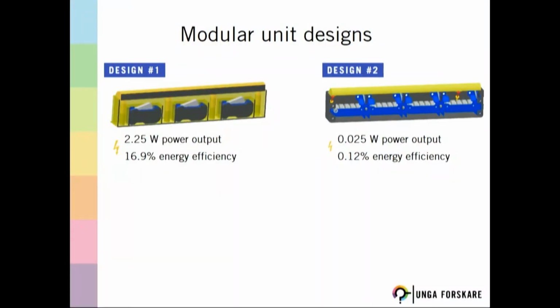For the second unit, I tried to make the dynamos myself using enamel copper wire and donut-shaped magnets. This unit produced a very disappointing power output of 25 milliwatt at an efficiency of 0.12%. The unit also required an actuation force of 98.1 Newton at an acceleration of 1 g. I suspect that the poor performance was due to short circuits in the windings of the coils, and also stiff mechanical members which made it difficult to operate the mechanism.